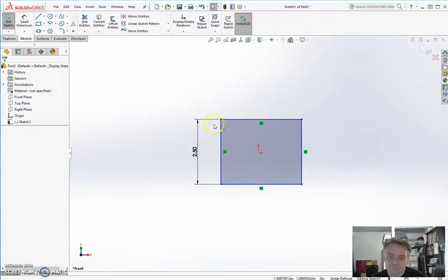And then the other way of defining your geometry is with constraints. So this line, I want it to be vertical. I don't want it to tip over sideways or something. So I use a vertical constraint. These little green things are the constraints.